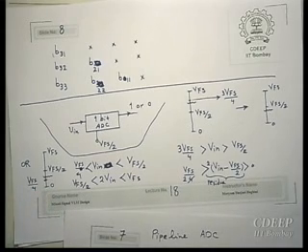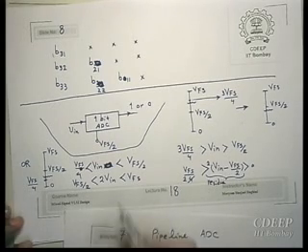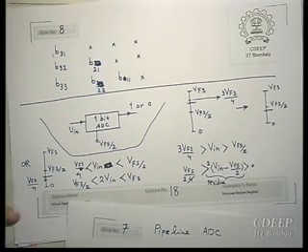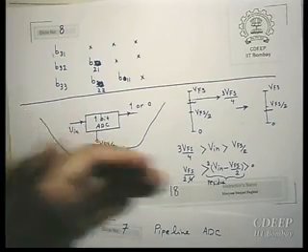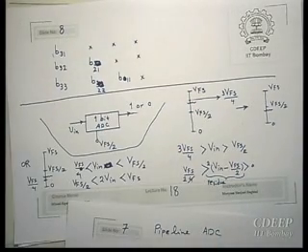Now what I have done is just scale up again by a factor of 2. So instead of comparing the input with V full scale by 4, I compare 2 V in with V full scale by 2. It's the same. So here the residue is the same as V in, and in the other case the residue is V in minus V full scale by 2.